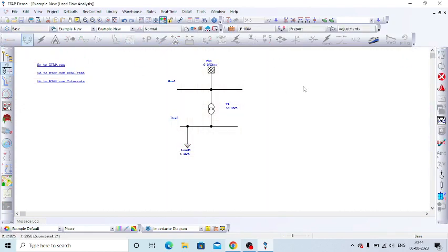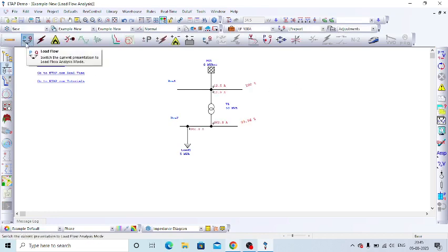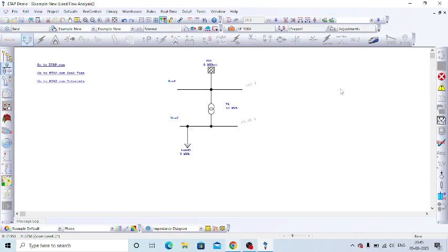For executing the load flow, we have to go to the PQ, that is the load flow. On the right side, PV is the load flow for a single run. If we need to do multiple runs, we have to turn the auto run on or off. Once we enable auto run, if we modify any values in the single line diagram, then the load flow will run automatically, so it will save some amount of time. So we can enable that.